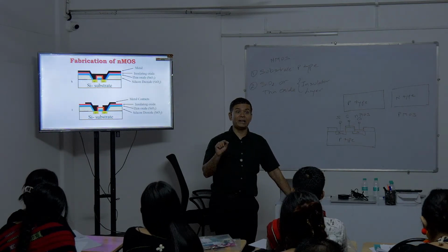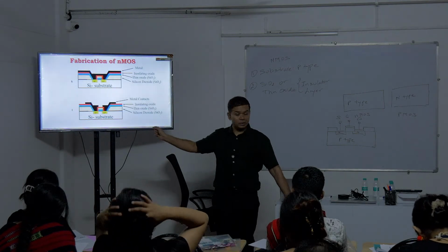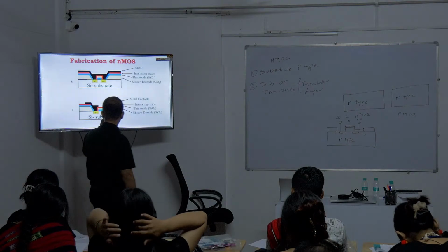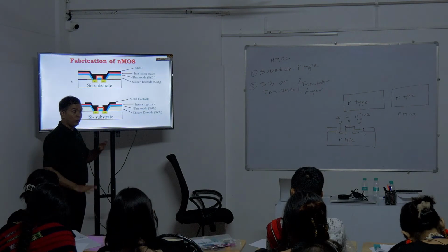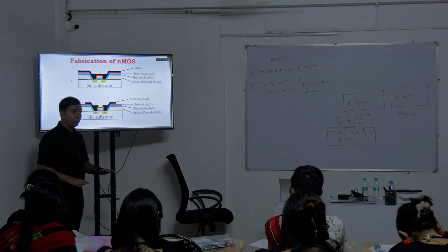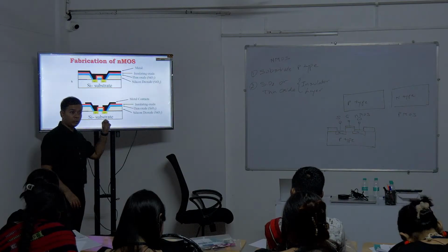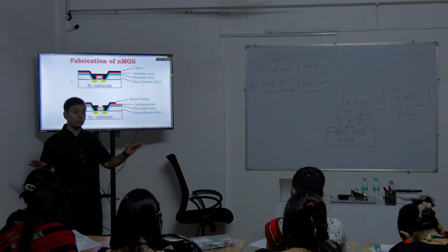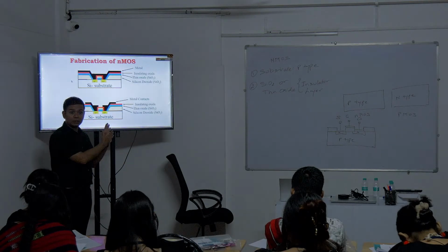There should not be any dust particle allowed. When these deposition processes happen between these layers, if there are dust particles, it is not going to work. No company can afford even a normal dust particle, and that is why we need a clean room. There should not be anything there when this device is fabricated.